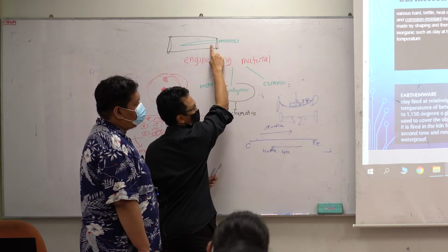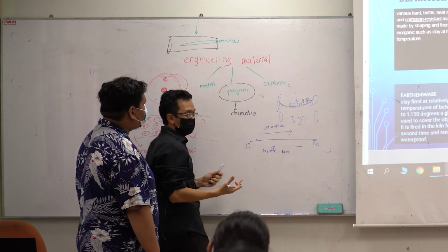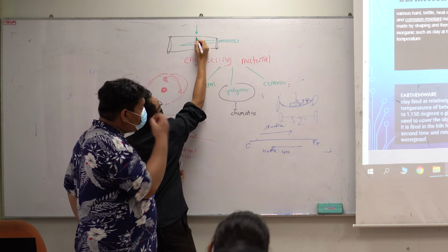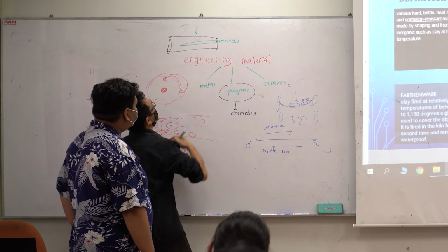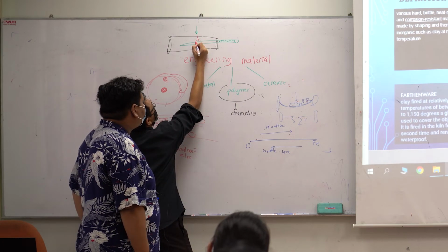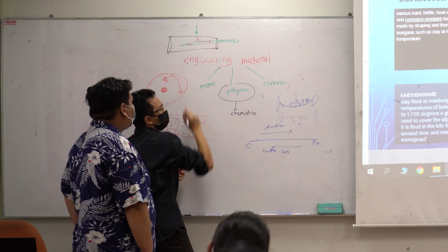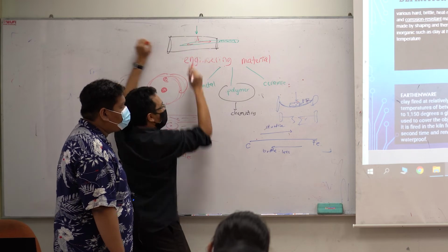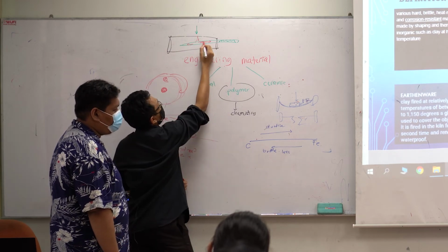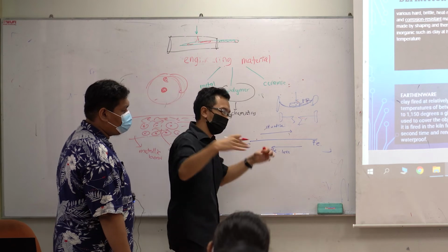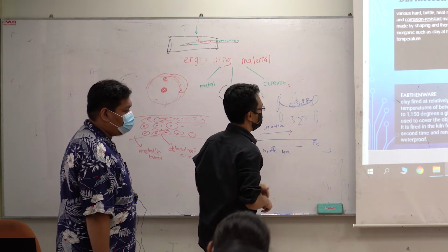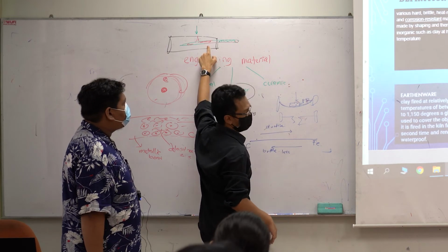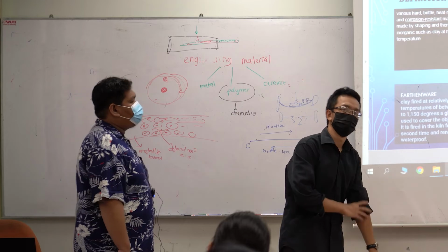But if you have this thing, if let's say a very high load is applied beyond the capability of this concrete, what will happen? You will see there are cracks. The crack will happen, but then when the crack reaches the metal, it will dissipate. So the engineer will have more time to see, because they can see the warning from the crack. Because the crack is arrested by this metal. The metal spreads the crack and so on, and that's why we call it reinforced concrete, because we use metal to reinforce the concrete. They use it in structural buildings and so on.